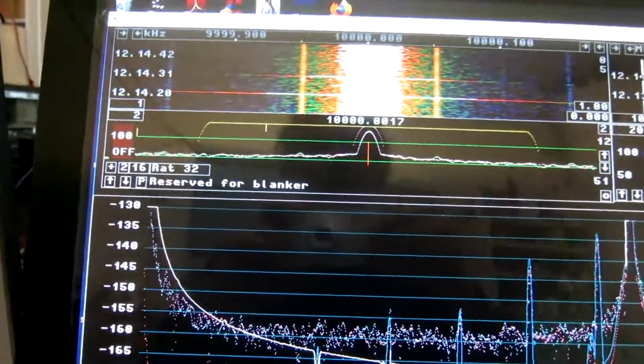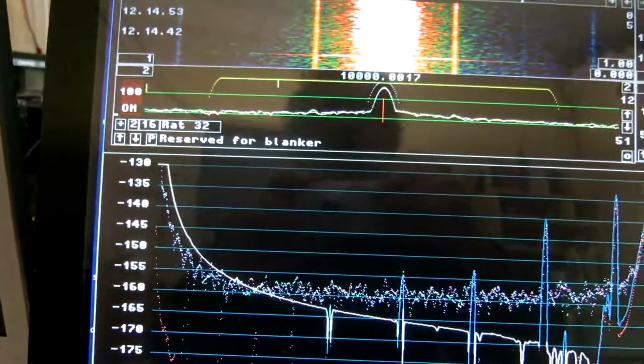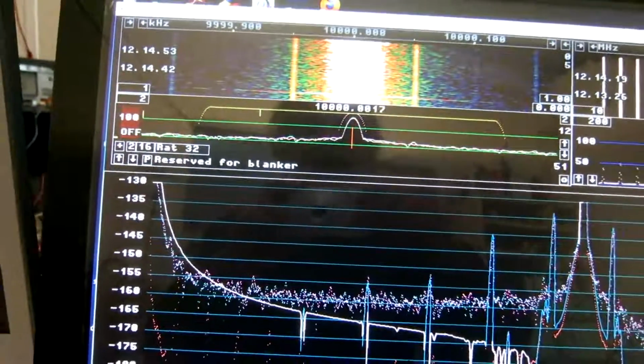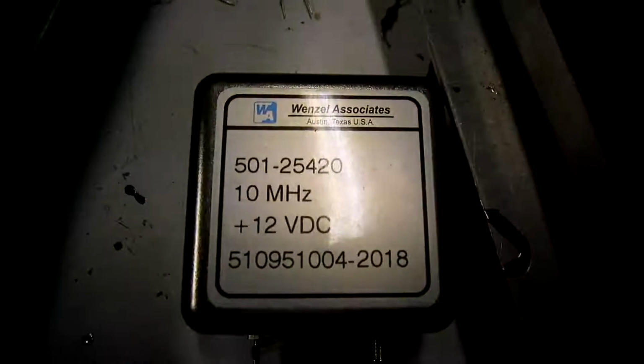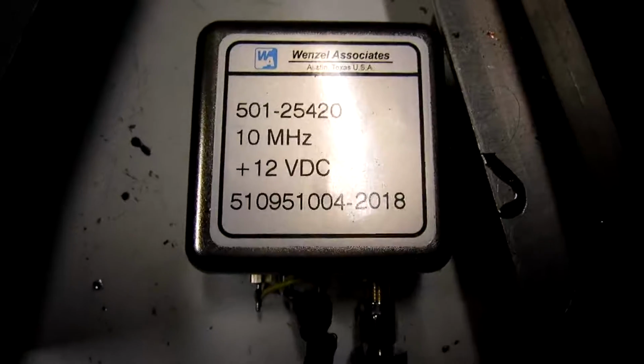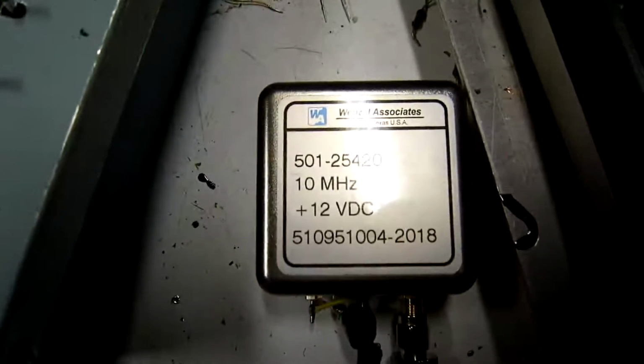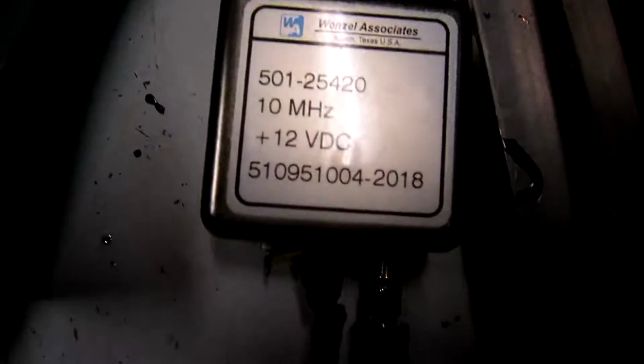Is it the crystals or is it in the amplifier? To find out, I will use the unit as an amplifier, amplifying a good oscillator. I will use this oscillator from Wenzel and run it through this oscillator configured as an amplifier. And then I can study what will happen at the different stages within this amplifier. But first I look at the correlation spectrum of the oscillator itself.